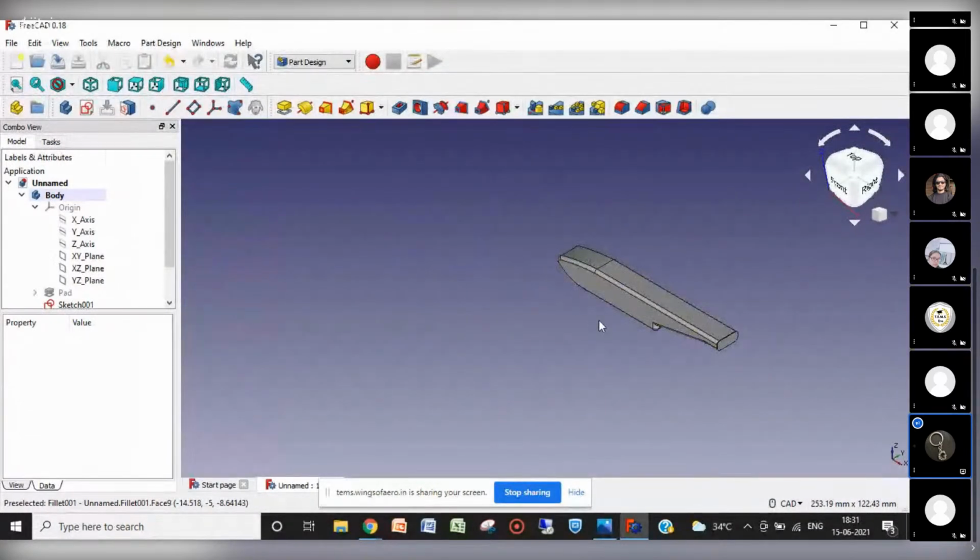Okay. And one more thing, these are always hollowed. These floats, or the skis, are hollow in nature. They don't have solid material. They are hollow, having air, so that it can be placed over the surface of water. It does not submerge, or only partially submerges, in the water. It can lift, take the weight of the aircraft and float over the water. That's why they are hollow by nature. And the material is somewhat like what is used in boats or ships.